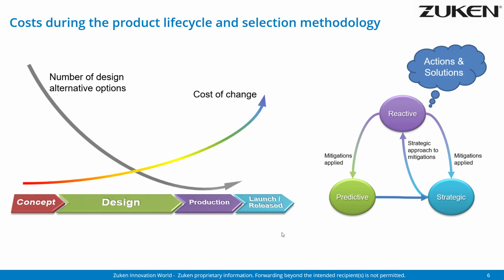From the predictive or proactive point of view, we need to gather information from the manufacturers about the end of life plan, looking at product change notification, end of life, and not recommended for new designs. And finally, from the reactive point, parts that are last time to buy or may already be end of life, we need to take action to solve any projects that already have those parts used in them, while also flagging the issue to other potential products and projects that are ongoing.